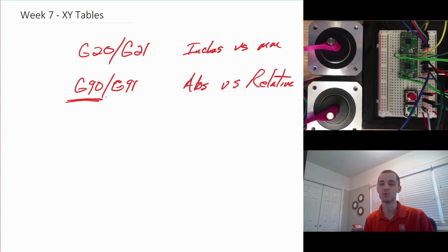So if you wanted to machine a part over here instead of over here, you could go 0 on that particular point, even though your machine home is over here. You could find out what the 0, 0 point is on that particular part and then do everything relative to that. There's also, which I'm not going to go into detail on, a whole set of commands where you can set up work coordinates and have multiple work coordinate systems.